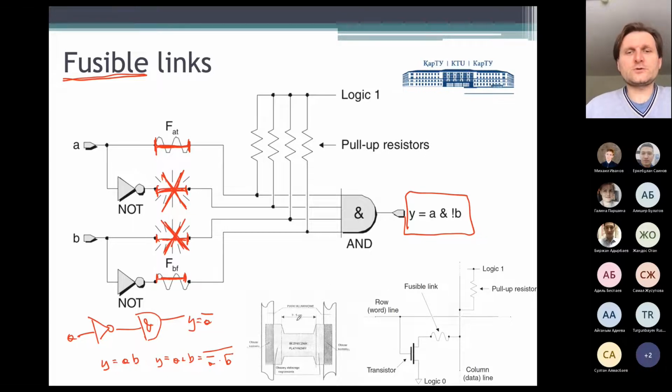The old structure of a fuse, as I mentioned, was the platinum fuse, and we may destroy the connection between two nodes. And nowadays we use a very small, very tiny silicon connection, or sometimes aluminum connection, and with high current we burn that fuse, so we destroy the fuse and make a gap. So there is the old technique and the new technique.